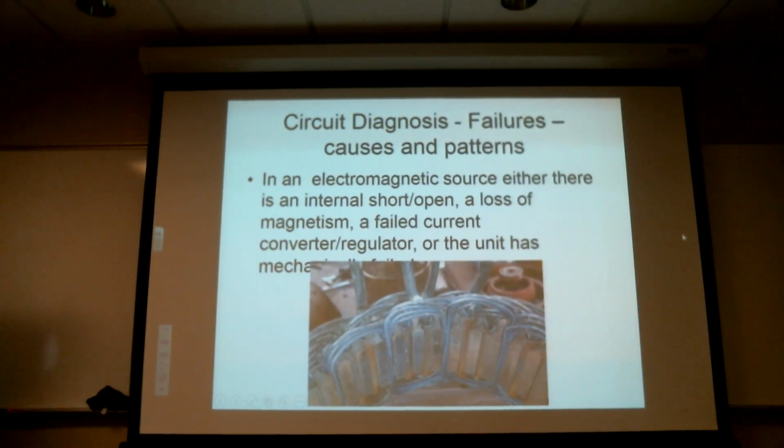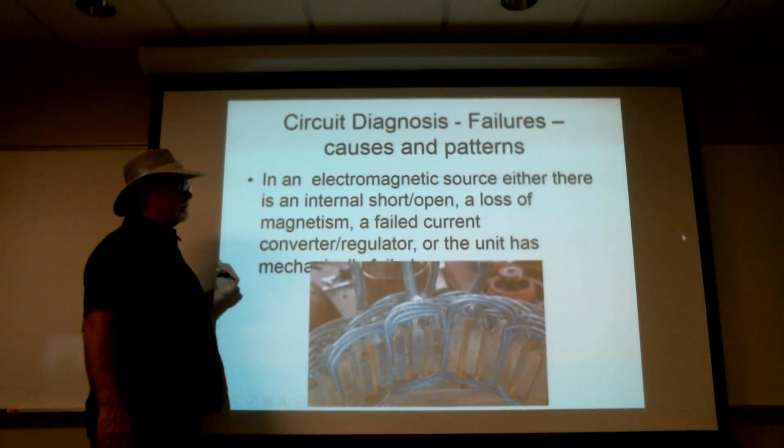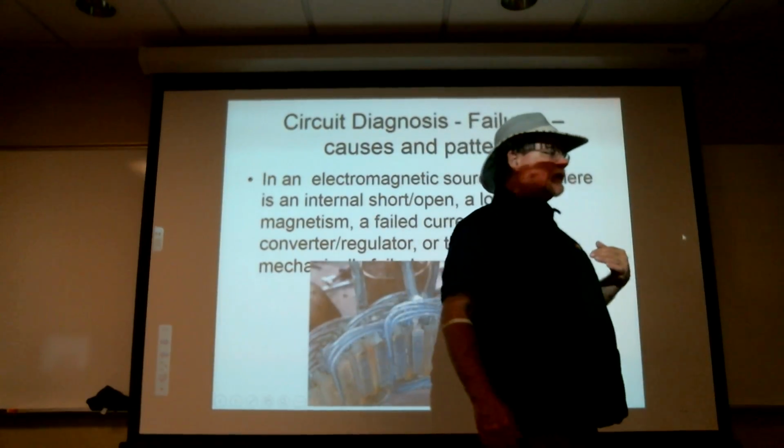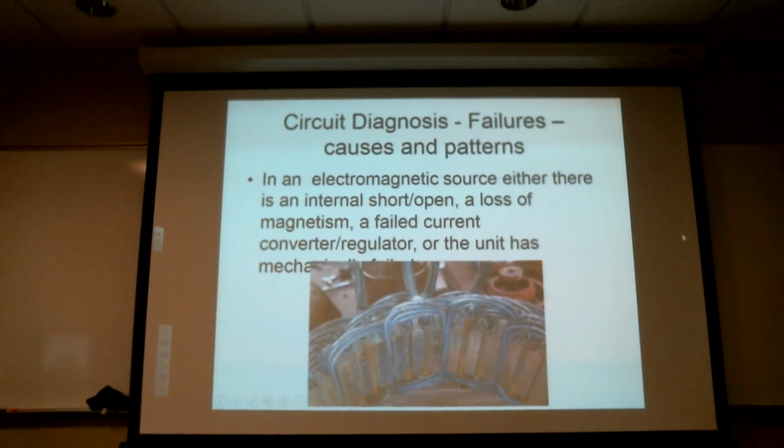So typically what's going to happen with these is the shorter open will take out one or two windings, and then things get hotter, and then the insulation starts to fail. I think one of the things we can say about a short is they are a testament to good insulation. They're pretty rare. Is that because the designers do a pretty good job of shielding things, because they secure the wires reasonably well? Don't know. Kind of all of the above.